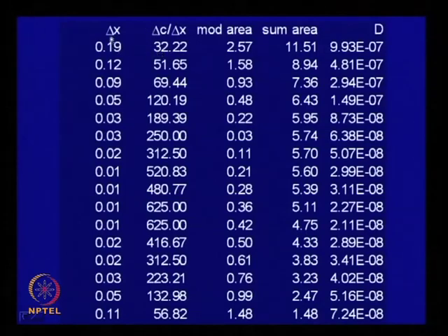Now you can try and find the slope of the plot. You divide delta c, which we have found, by delta x, which you can similarly find, and the ratio of the two gives you the slope of the plot. When you calculate this area, you have to ignore that negative sign, because the total area gives you that amount of mass transport.